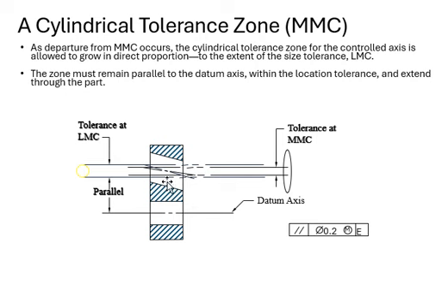Least material, the hole size is bigger. And of course, depending on the hole size, your axis varies. Whatever that is, you still need to maintain these two axes parallel to each other, meaning when you manufacture or draw the design, avoid as much as you can varying too much from that zone.